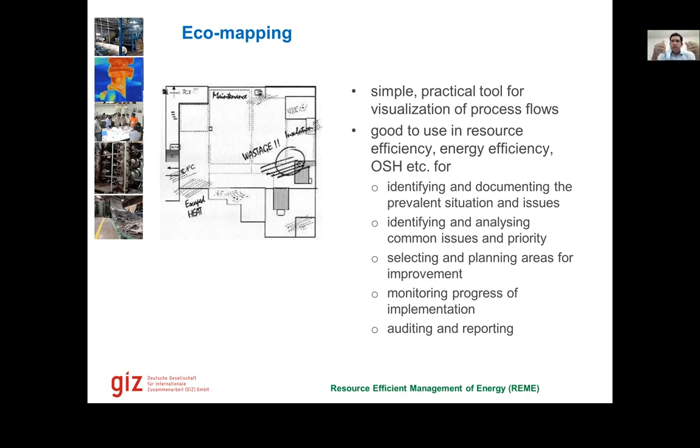So normally when you go to the factory, more than 50% of their energy losses are visible. You can see if there are uninsulated surfaces, you can see if there are leakages, you can notice if there are noises in the motor, for example, or if the pump is knocking, if there is knocking in the steam pipes, for example, if there is air emission going out, if the water discharge is hot or not. There are so many issues which you can identify only visually. More than 50% of the problems are visible. So you go there and only identify. You don't need to quantify at this moment.